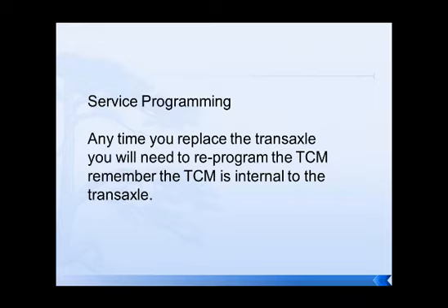Okay, guys, we should be ready to roll here. So service programming, let's talk about service programming for a minute. If you replace a transmission, a 6T70 or 6L80 or whatever it happens to be, you're going to have to program this particular transmission to fit that application. So bottom line is that it will not work in the vehicle you put it in unless you program it. So just keep that in mind on any of the 6-speed transmissions. Since the TECM is internal to the transmission itself, it has to be programmed for the specific vehicle that you put the transmission in.